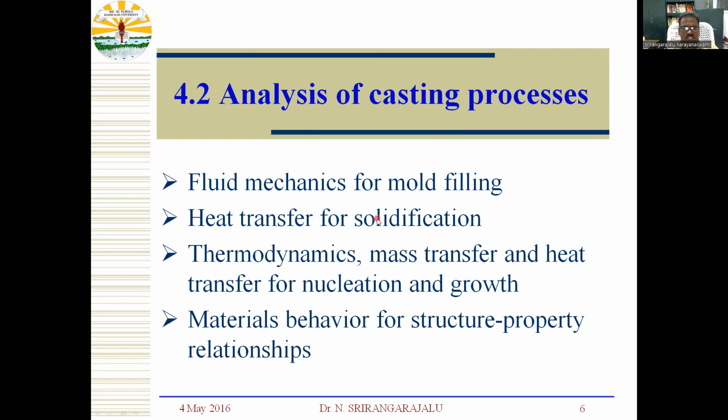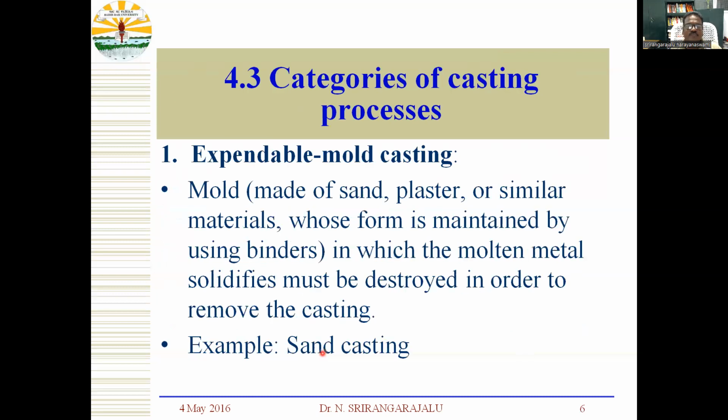Analysis of casting processes includes fluid mechanics for mold filling, heat transfer for solidification, thermodynamics, mass transfer and heat transfer for nucleation and growth, and material behavior for structure-property relationship. All of these are incorporated, and then only the casting process will be obtained.